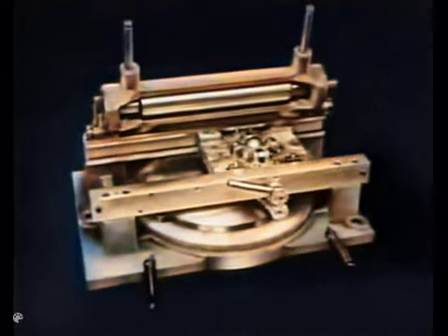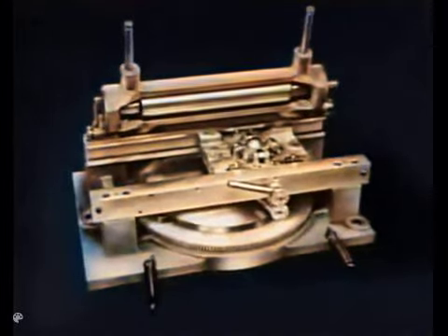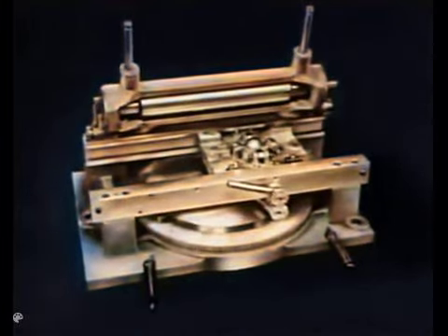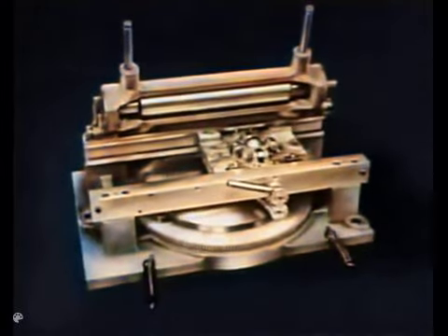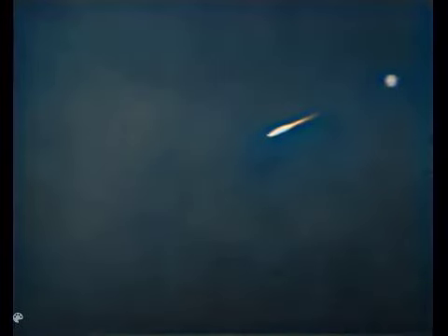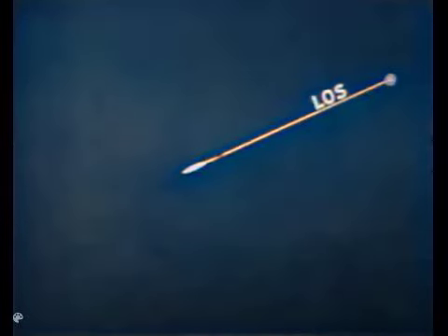This is a disk-type integrator, one of several different types. They can do many jobs. One of the simplest, the job in range keeping, will give you a pretty good idea of what an integrator can do. An elementary example of range keeping is one with stationary target and with own ship moving at constant speed along the line of sight. The problem starts with an observed initial range.